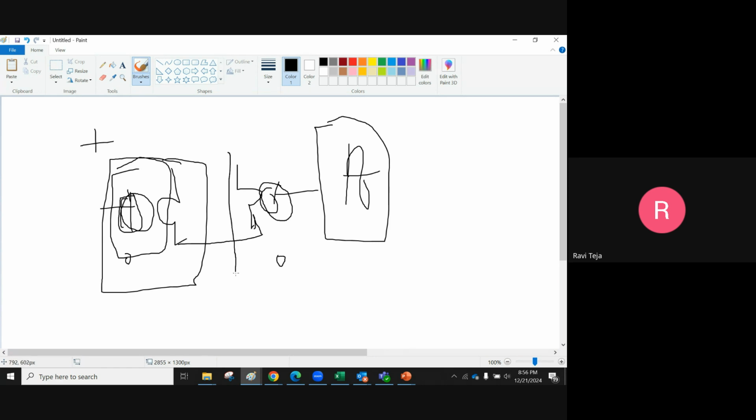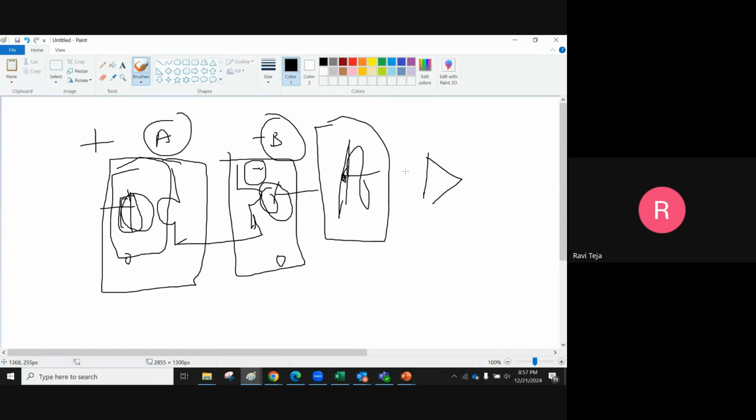Okay, all the parasitics like resistance, capacitance, and everything, like device placement and everything. If I take this as A and this as B, then A and B should be matched perfectly. Only then we will get the desired output. So here in an op amp, what we can understand is that the differential pair is very critical.